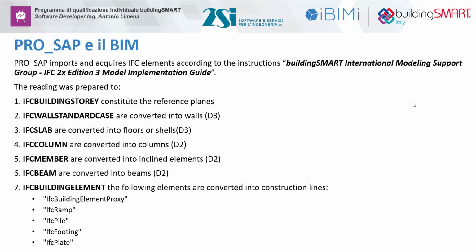So, first of all, we have to say that ProSAP imports and acquires IFC elements according to the instructions of the buildingSMART International Modeling Support Group. Specifically, here we talk about the IFC 2x3 model, but it actually also imports IFC files of the version IFC 4, so the latest one, but it doesn't change much basically, because IFC 4 just added some new entities that describe detailed elements, so it's something more important for architectural modeling and